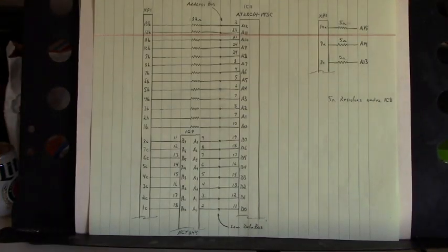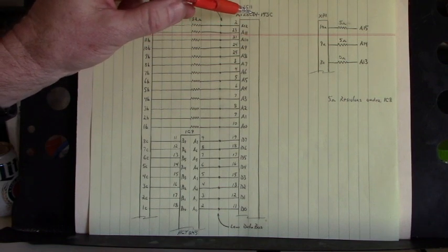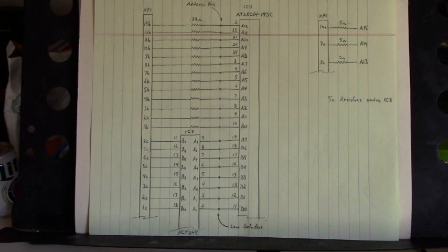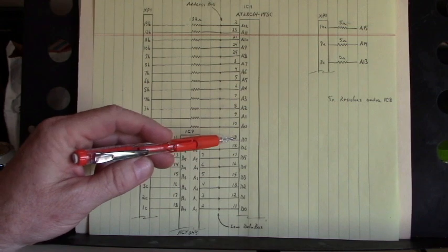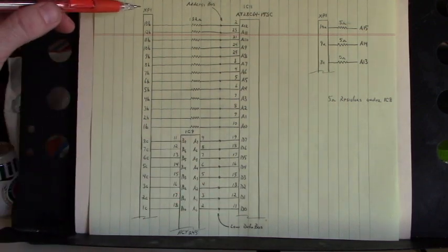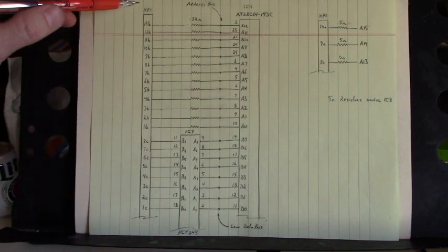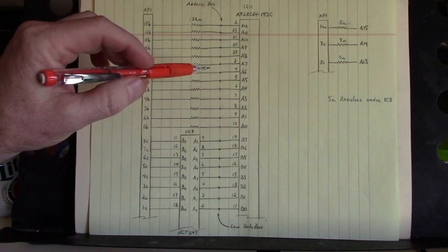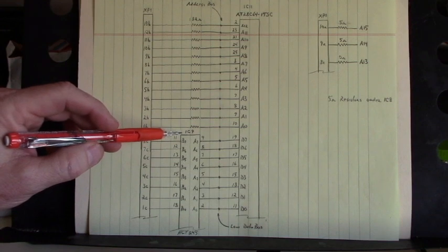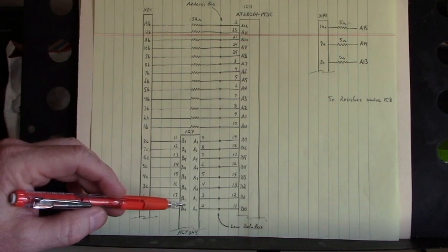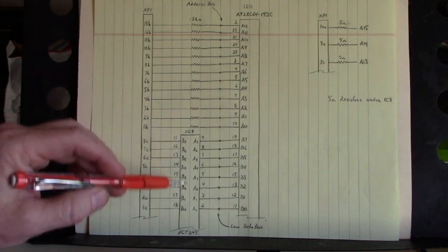Now we're inside the Indramat software module. Here's the AT28C64-15SC. Here's the address bus. Here's the data bus. Here's the XP1 connector. That's that connector that we have to mate the Indramat software module to our programming adapter. Now, down here is the 74HCT245. That's our bi-directional octal buffer.